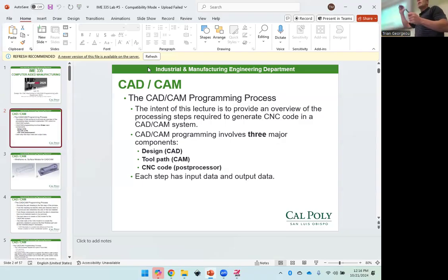It basically sets up where that tool is going to go in the CAM. So we pick our toolpaths. And within those toolpaths, we've got our basically, I'm going to write F and S, that's the feeds and speeds. It's got all the variables for cutting within the CAM portion of it, right? Depths of cut, step over, finish passes, and so forth.